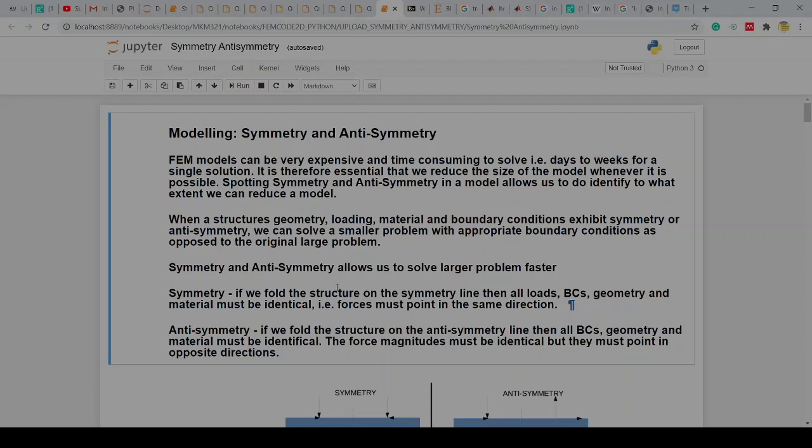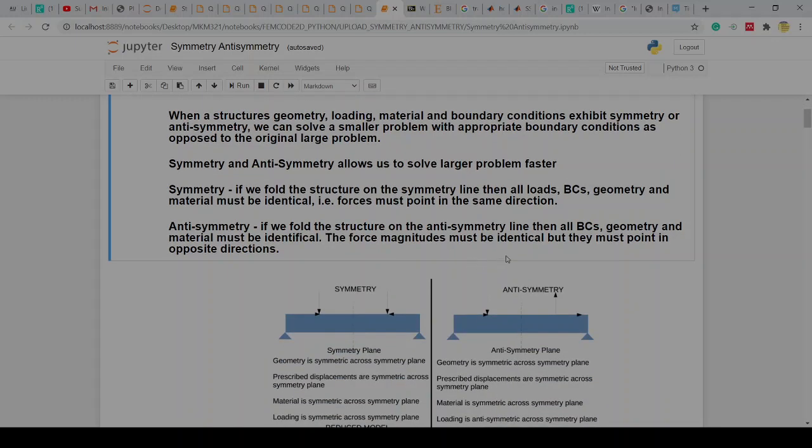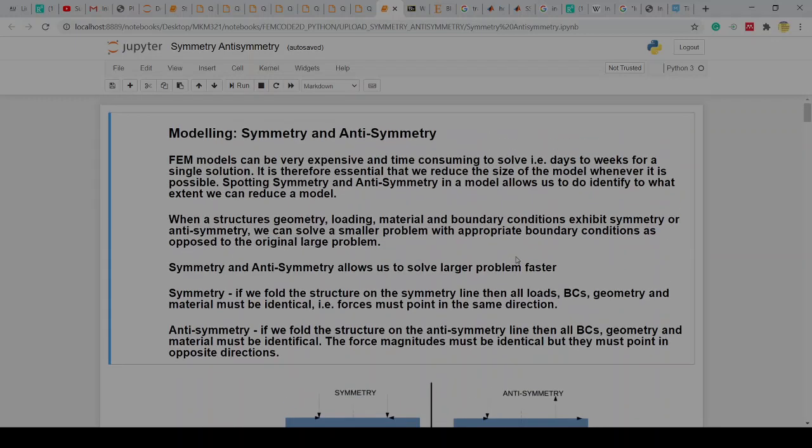The bandwidth doesn't necessarily stay constant, and in that case, things can scale quite significantly. Okay, so then essentially things can be driven by n to 2n. So that scale that's double as long as what I have to wait if I have twice as larger system. But if the bandwidth, that's the best case scenario, if the bandwidth stayed the same, so I'm saving half the time by employing symmetry when I reduce this system by half, or 4 times the time if I reduce it by 4. But if the bandwidth also changes as a function of the problem size, then there's additional savings.